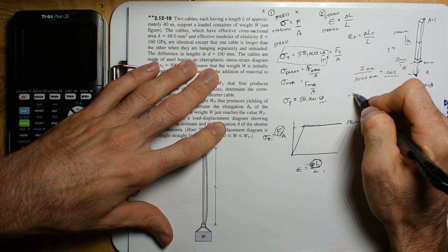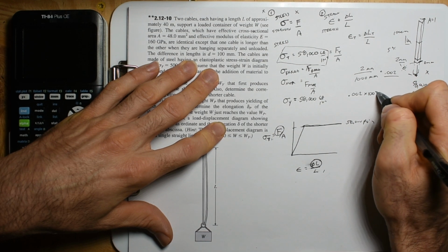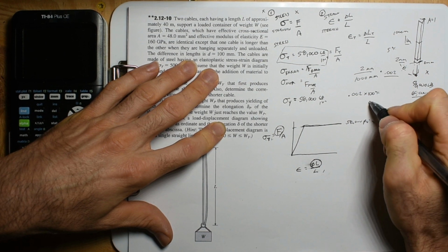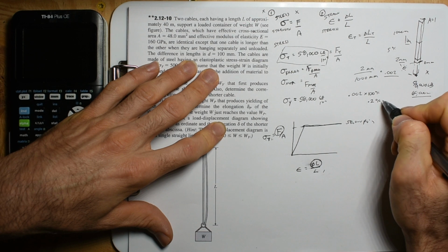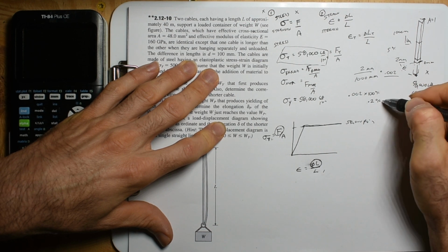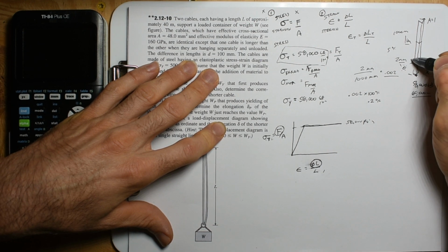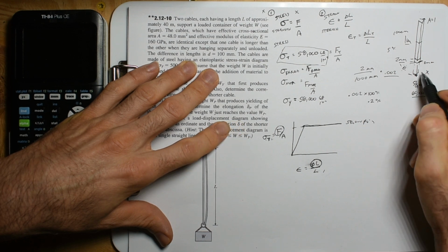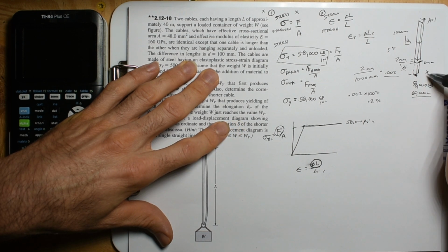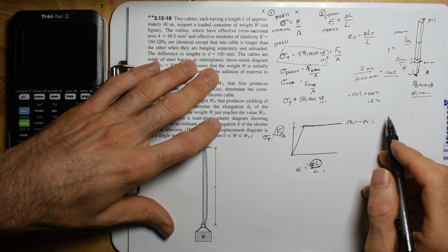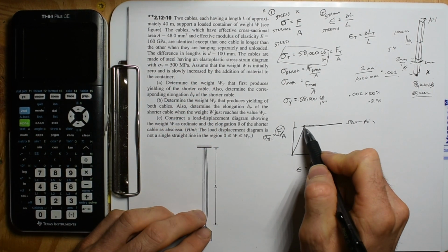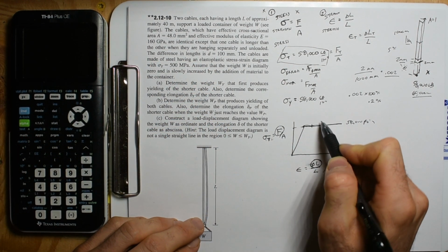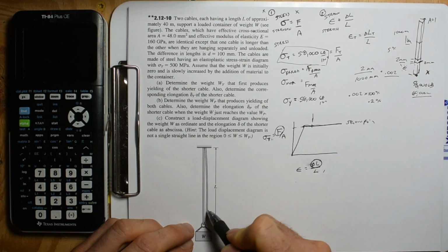That's why I always take this number, 0.002, times 100%, and then you're like, oh okay, that's 0.2%. So if I know the length, 0.2% of the length is going to be my max change in length before it turns into plastic and people lose their lives. You know what I mean? But for some problems, it's okay to hit this plastic region as long as you've got something else backing it up, like another rope.